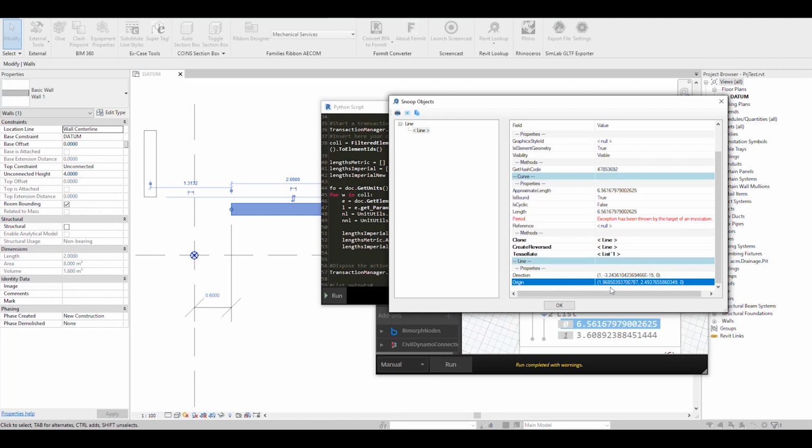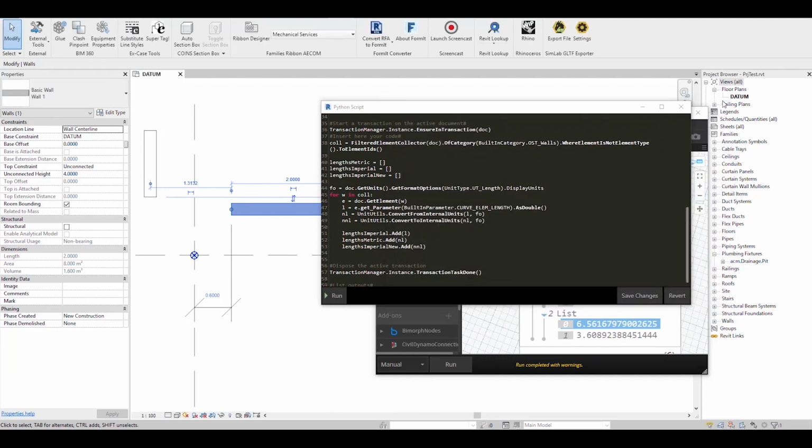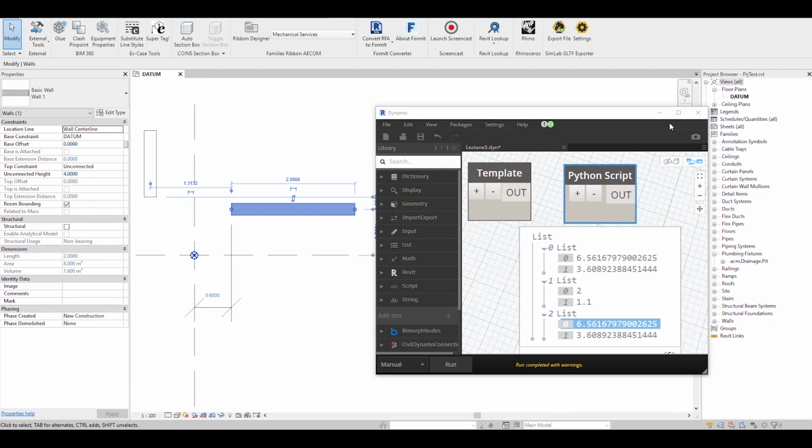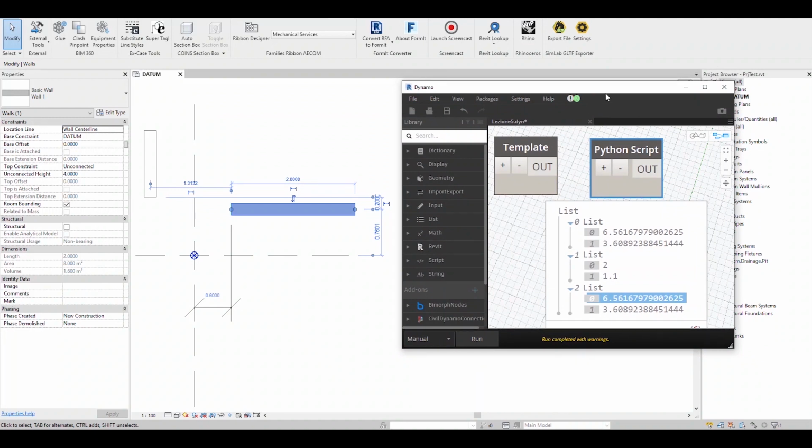And that means that this value is also in internal units, like the length. And so if I want to know the X and Y of this object, or if I want to place an object with specific X and Y, I need to convert into or from the internal units. So just bear in mind this one when you try to use Revit, because you might end up getting the wrong location of the object, and that's due to the internal units. So that was kind of a way of explaining how we can get this right.